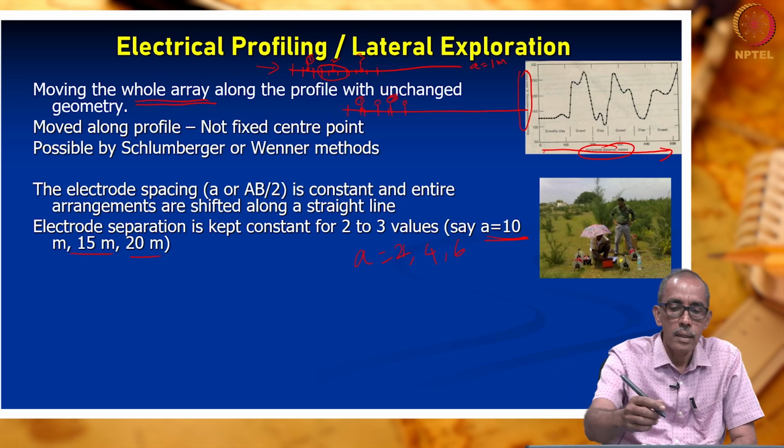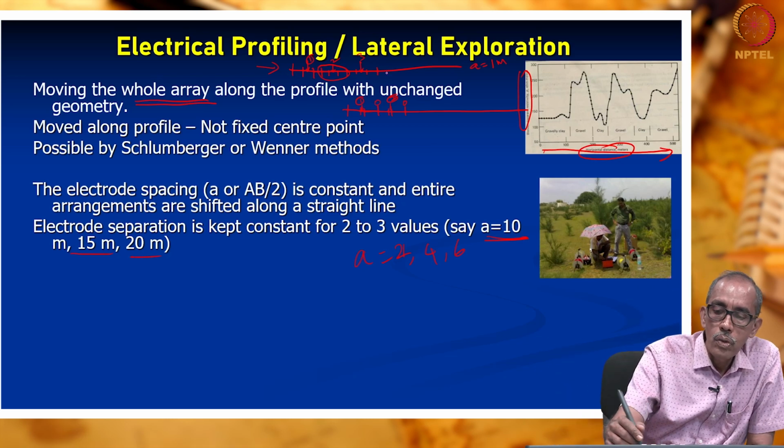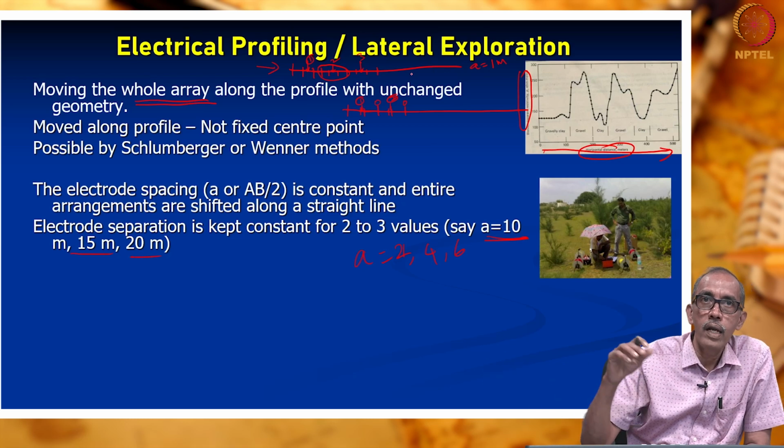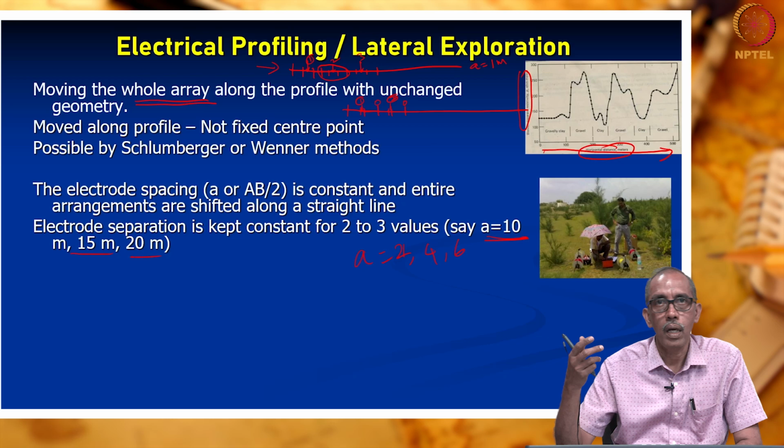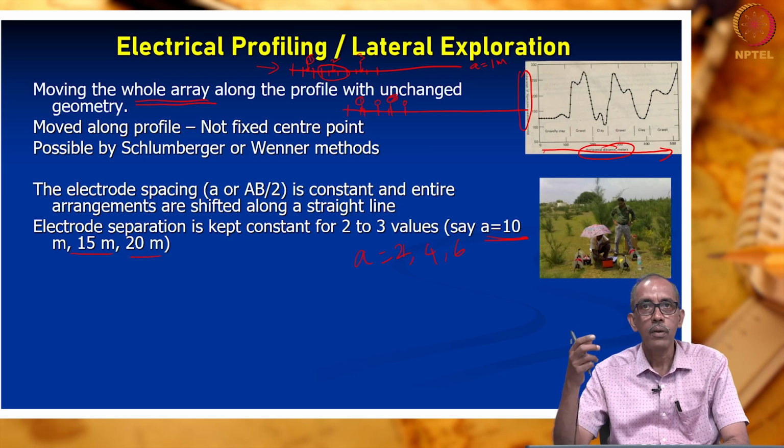How do we do that? That means first let us do a profile for 1 meter, then repeat the profile with 2 meters, with 4 meter A spacing and so on. Okay. So, this is how the survey will be carried out in electrical profiling.